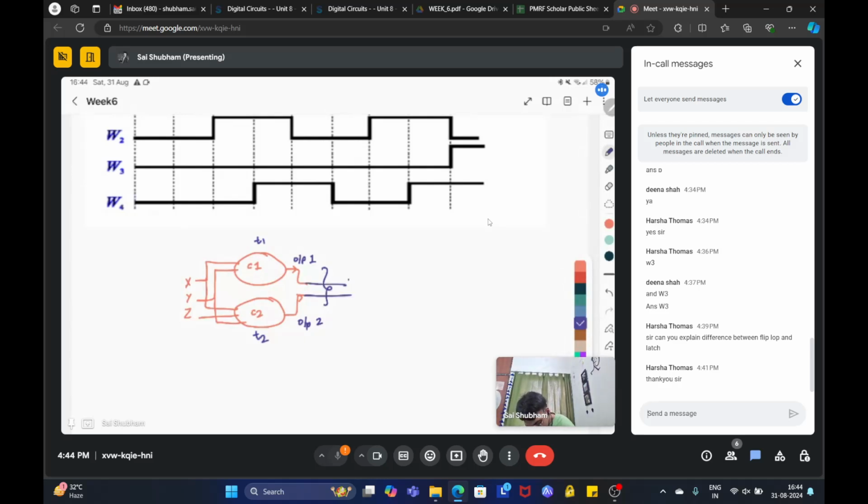So what will happen is that if there is a circuit over here, the output will fluctuate. Suppose initially it was 1 1, fine, and the output was 0, but it took the C1 circuit more time to process, and later the signal came from 1 to 0, so the output becomes 1. So if you do not have flip-flops in your circuit, your output will keep on fluctuating.